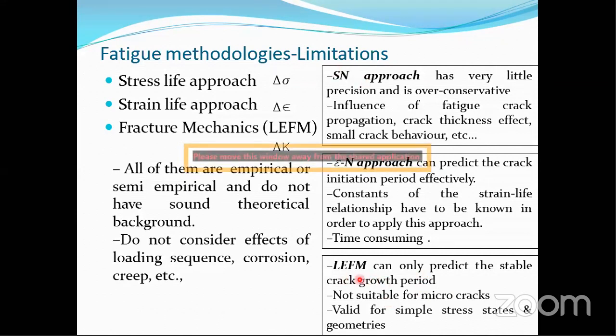So most of the industries limit themselves to the SN approach and LEFM approaches, and LEFM especially when they find a crack during regular maintenance. Even in aircraft, if we observe very closely, many cracks can be seen. But we have to see the size of the crack and the loading that crack is taking, because we cannot rule out failure even based on the size.